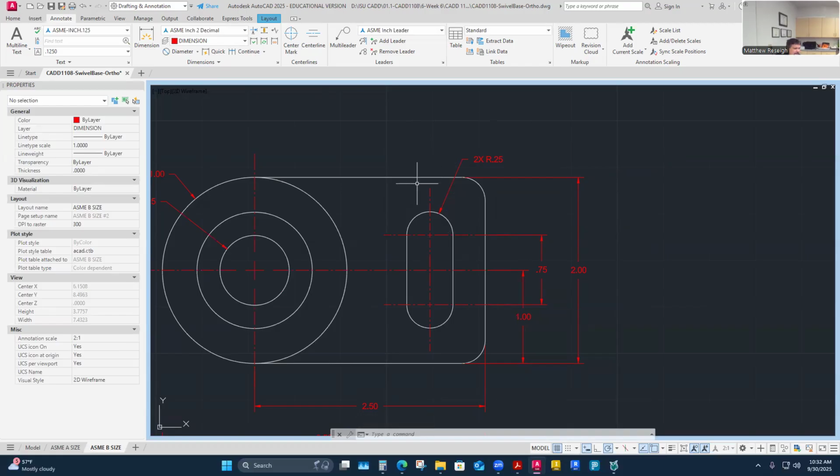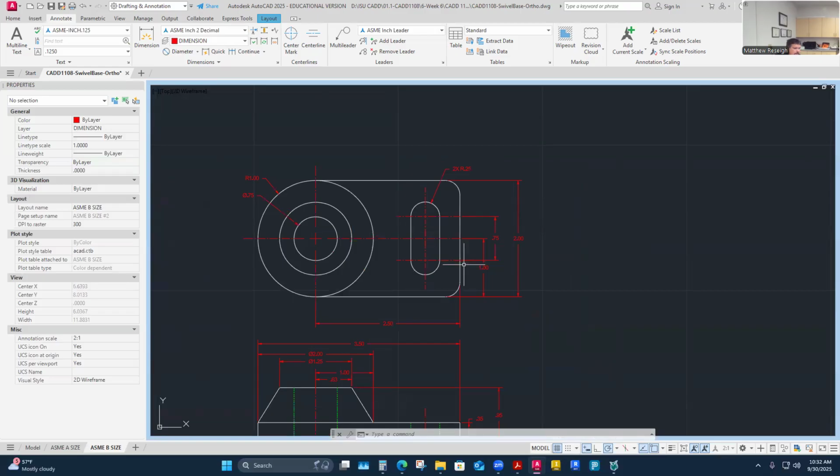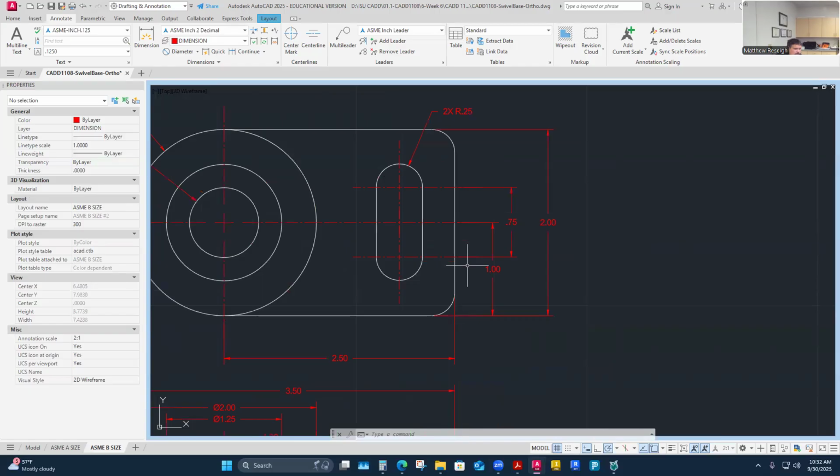And then I just need to locate that. So locating it, well, I would think of where's my control. For sure, I'm establishing control of this part from center. I think I already decided that I liked the 1 inch from center over. And so maybe I would control the slot from center, like this center line, rather than from an edge. I'm definitely not going to choose the back edge. Like I could, but I really haven't pulled any dimensions from the back edge.